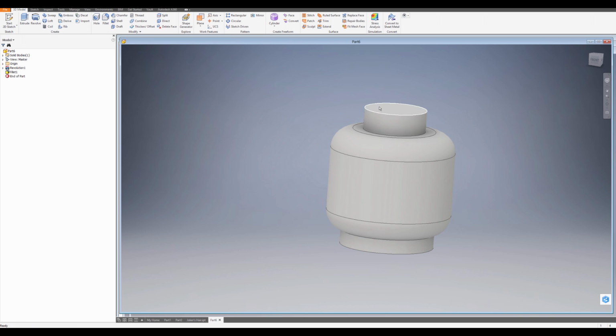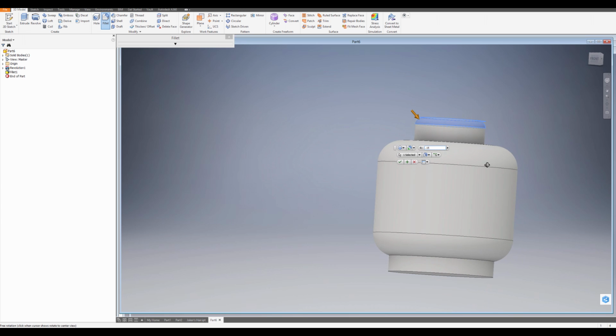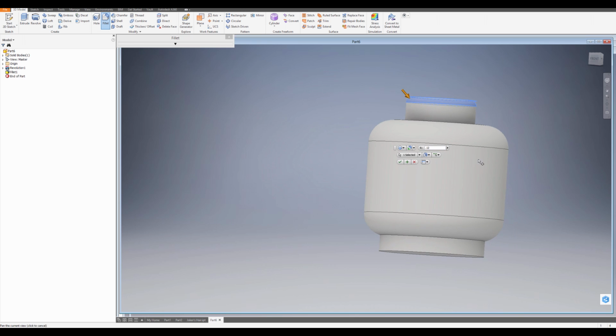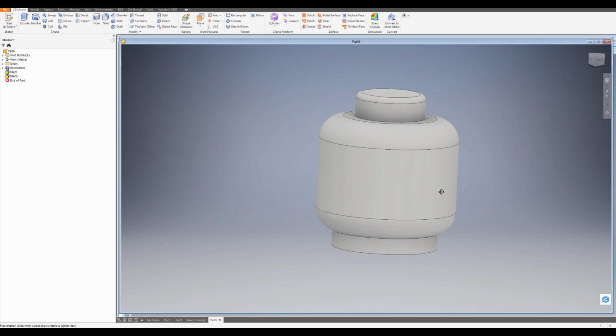That's been created. Now let's add the small fillet on the top portion. So fillet, click on the top portion, and 0.6 or 0.5 would be way too much for this. So let's start with 0.2, and that's a little heavy, so 0.15, and that looks a little heavy still, so 0.12, much better. Okay, and that's it. I'm going to hit OK, or the green check mark.